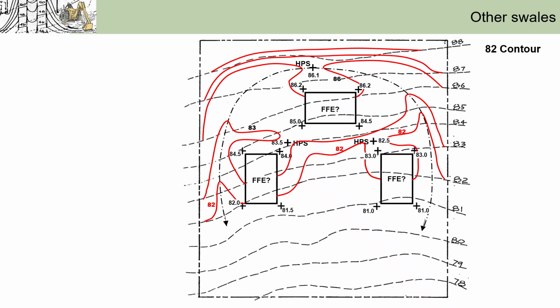the left. Now, in order to find out where exactly the contours hit the building walls, basically you'd interpolate between the two building corners. For instance, for the building on the right, the two corners are 83 and 81, so 82 should hit the wall right in the middle. Okay, so interpolate between the two corners based on the green line distances.